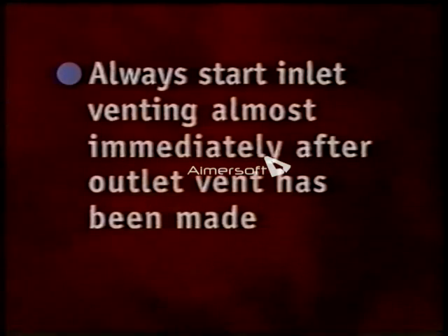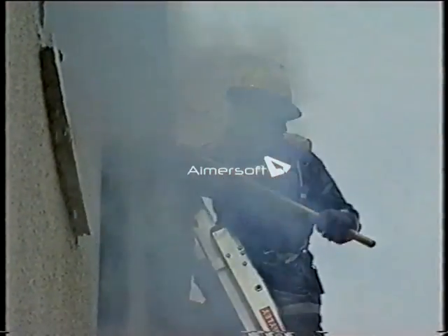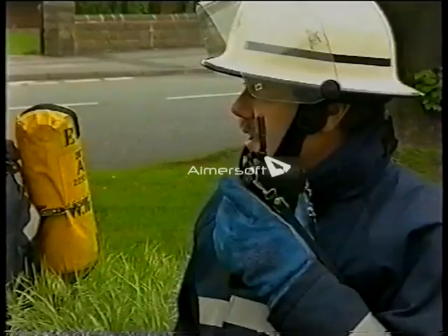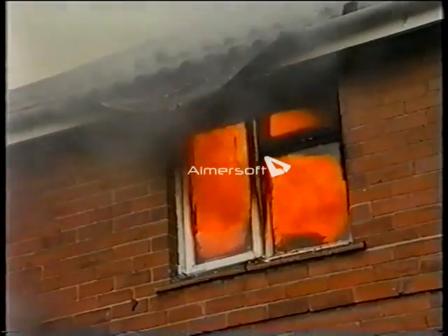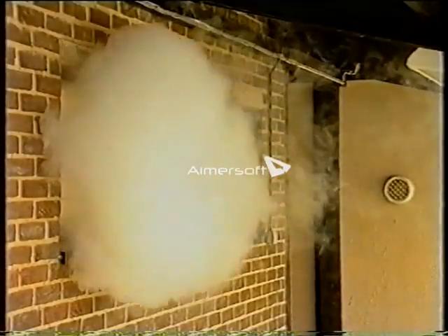Always start inlet venting almost immediately after the outlet vent has been made. At all times, the effects of venting must be closely supervised, and progress inside the building must be reported to the officer in charge. Used incorrectly, it can worsen the incident and even lead to loss of life. But when used carefully, it can have enormous benefits for everyone.